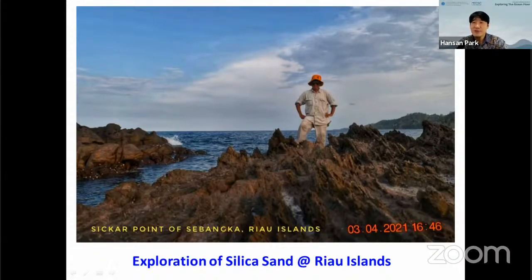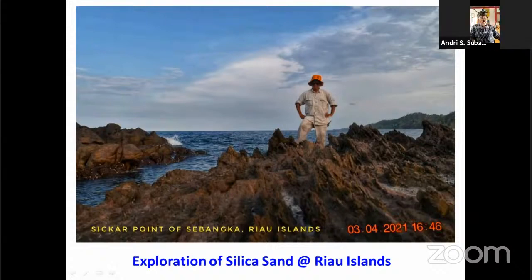Yes, I also have that worry about using our equipment to survey that. The SBP has only 40 or 80 meters of penetration depth, and a paleo river may lie under deeper sediment. So as a recommendation from Dr. Kim, we need more equipment, like a sparker. Mr. Hansan, maybe I ask one more question.